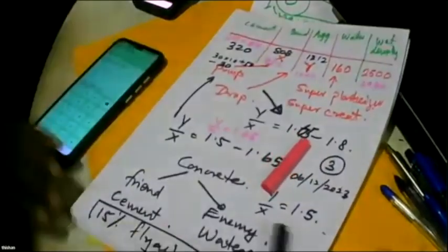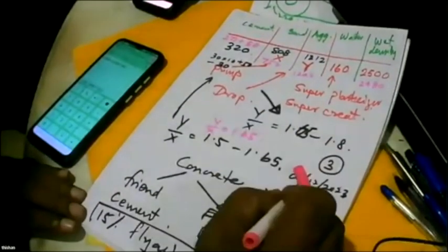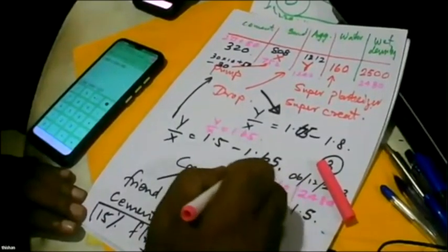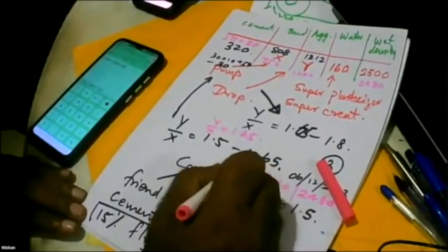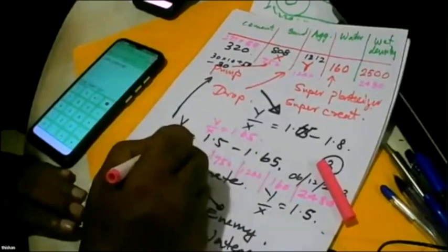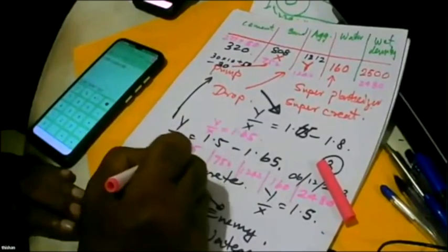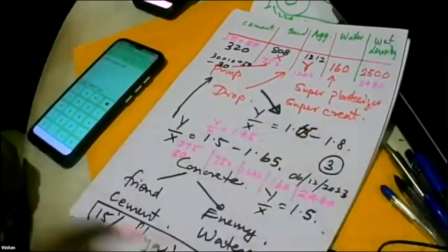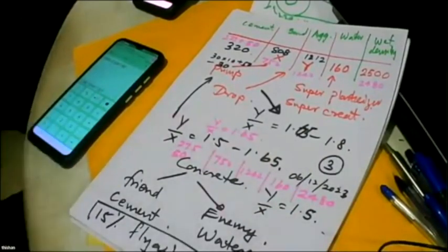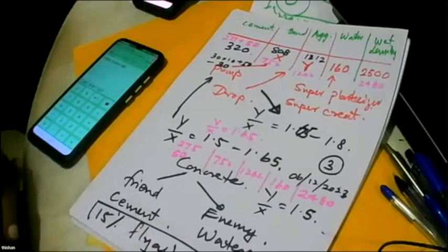So you can see the numbers are 2480, 160 water, 1242, little more aggregates, less sand. What is the main difference? 275 cement, 50 fly ash. What is the maximum temperature that this will reach? The maximum temperature of this mix will be 70 or below 70. Can you see how to think about optimizing the mixes? Is that clear?